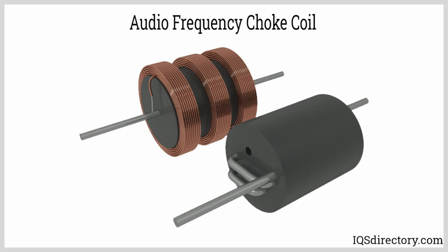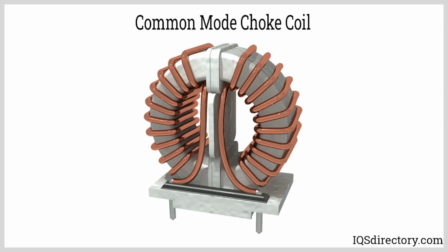Operation stages. Choke closed. When fully closed, the choke minimizes the air intake, making the mixture very rich. This is usually necessary for cold starting. Choke partially open. As the engine warms up, the choke opens partially, allowing more air to enter the engine, thus leaning out the air-fuel mixture.